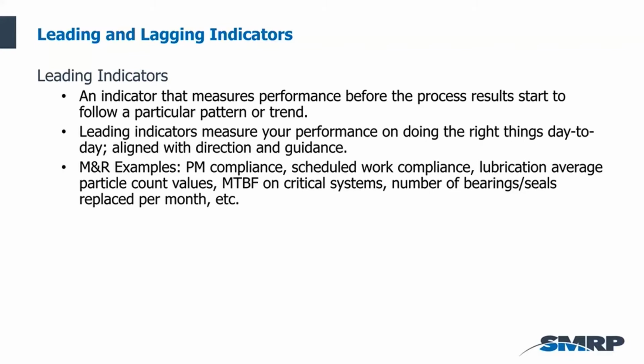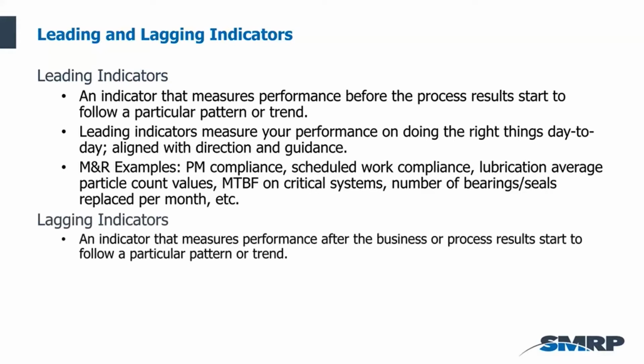Some examples are things like PM compliance, scheduled work compliance. You might even look at things like lubrication average particle count values if you're trying to improve your lubrication program. Mean time between failures on critical systems, number of bearings and seals replaced per month.